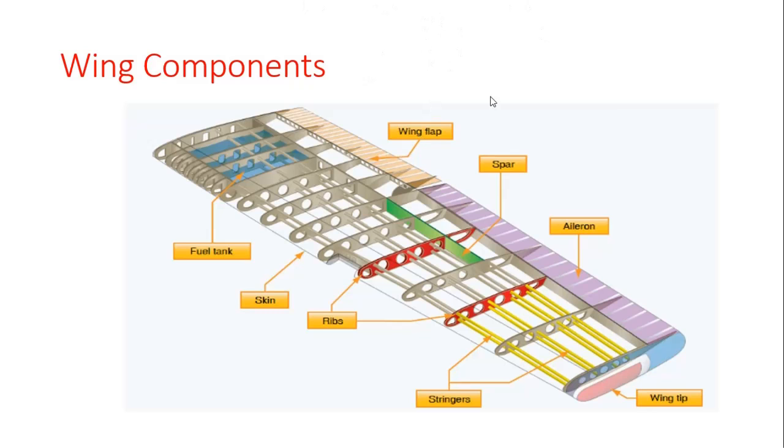Next, flap. Flaps extend outward from the fuselage to near the midpoint of each wing. The flaps are normally flush with the wing surface during cruising flight. When extended, the flaps move simultaneously downward to increase the lifting force of the wing for takeoffs and landings.